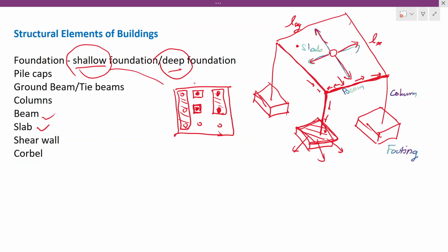So if we have low bearing capacity and considerable load, we may not be able to put a single pad footing. Then you might need to combine. You might even need to combine several footings together to get a higher area for the foundation. With that, you can have a foundation for smaller bearing capacity. When you have a smaller bearing capacity, you have to increase the area of the foundation, because your bearing capacity is small, right? Let me explain that a little bit more.